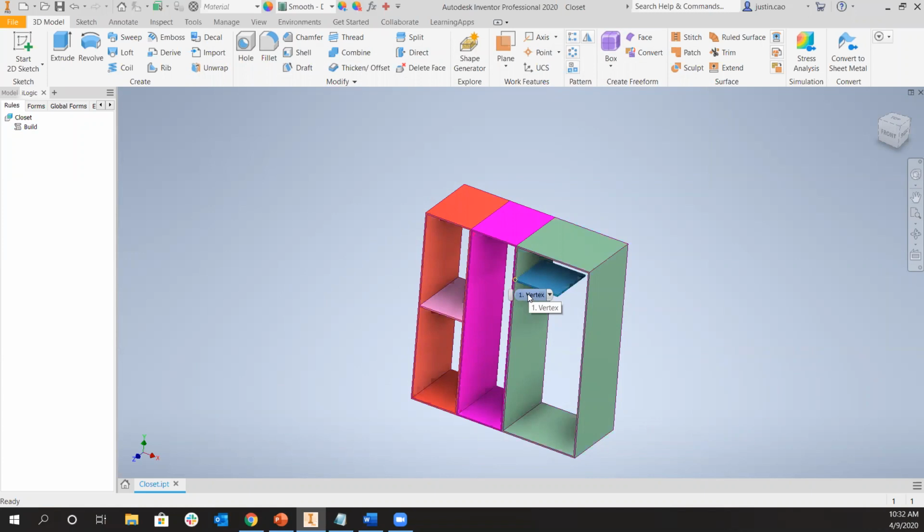You can use work points if you want. Sometimes you can use suppression, like what Justin showed with the suppression of certain components, to be able to locate, suppress and unsuppress the locations of the components, and then do a switcheroo of whatever those components are, depending on the situation you want. It can get very, very complex, and you can do a lot of things with the configuration. Yes, sir. So as long as you can locate the point where you want to put it, you can utilize some of the logic on the back end to be able to move things around.